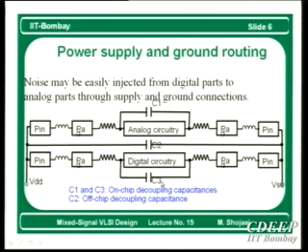What do these capacitances do? See, when I have a current and this is a switching current, this switching current will flow through the inductor and will create a problem. How can I divert this switching current to come from somewhere else? This is the reason we put this capacitor. How does it work? If you consider the DC value of this capacitor and assume this capacitance is very large, the DC value stored on this capacitance is VDD minus VSS.